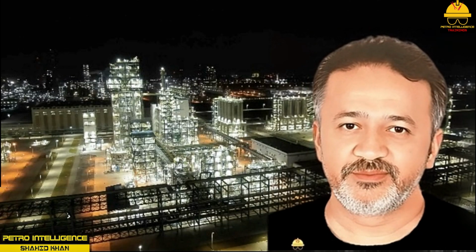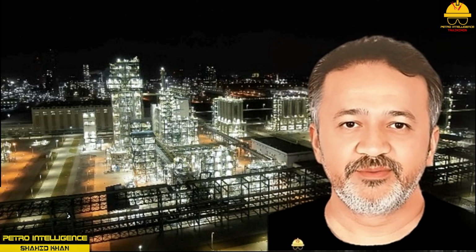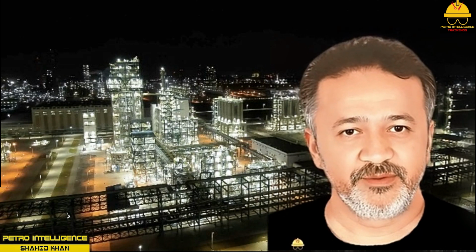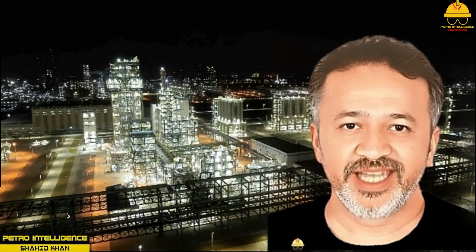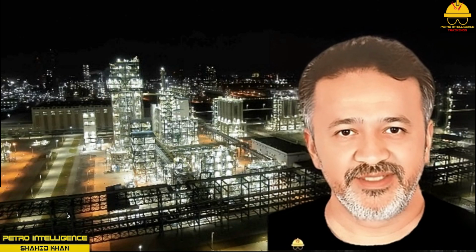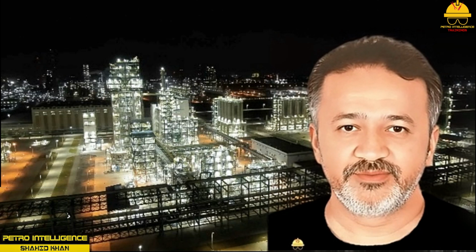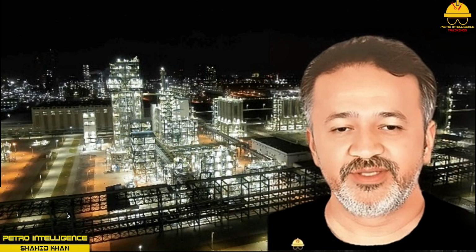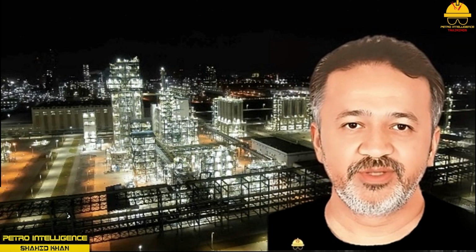Temperature symbols. Temperature symbols are typically represented as TI for temperature indicator or TE for temperature element. A temperature indicator is typically a gauge or a thermometer. A temperature gauge has a bimetallic strip inside that differentially expands with increasing temperature, creating a deflection that is correlated with temperature. These instruments are located in the field next to the equipment. Temperature elements are typically thermoelectric temperature measuring devices, thermocouples, thermal bulbs, resistance bulbs, or resistive temperature detectors, RTDs.